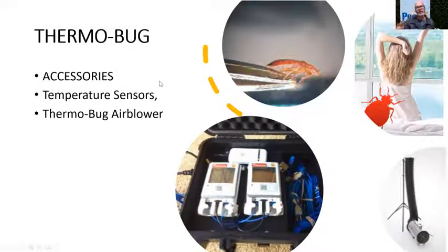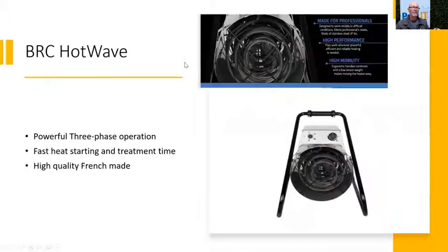Down the bottom right hand of your screen there, you'll see a sort of snorkel and a fan. That's a different style of fan. It's actually going to draw air downwards because as you heat up a room, your heat is going to be moved right to the top. Above your head, it might be 65 degrees, even 70 degrees. And that snorkel or blower is sucking air down and redistributing it at ground level. So that's a great system as well.